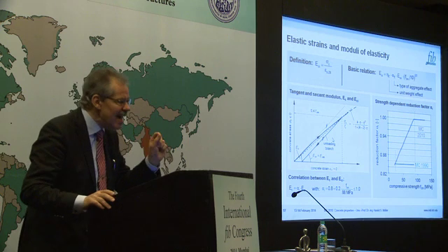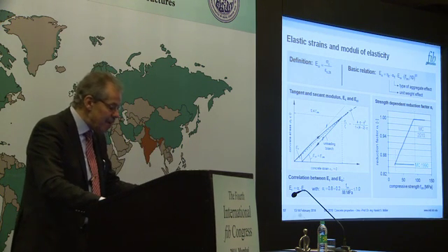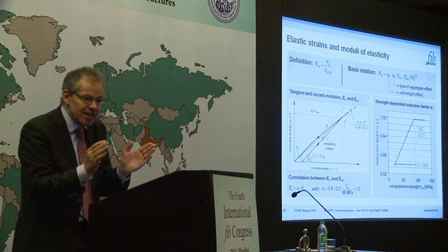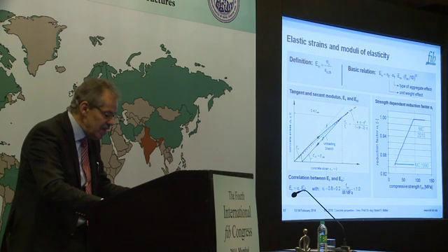You need the secant modulus of elasticity, which includes some plastic deformation which initially occur at the first loading. And this is shown here in this relation. You have here the initial modulus of elasticity, or the tangent modulus of elasticity. You have to multiply it with a factor alpha to arrive at the secant modulus of elasticity. This is this one.